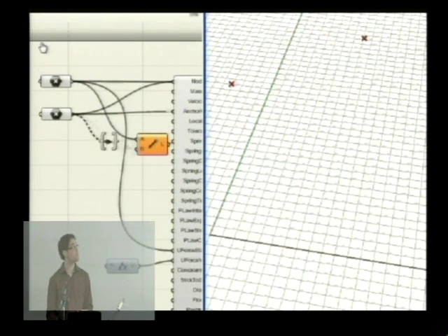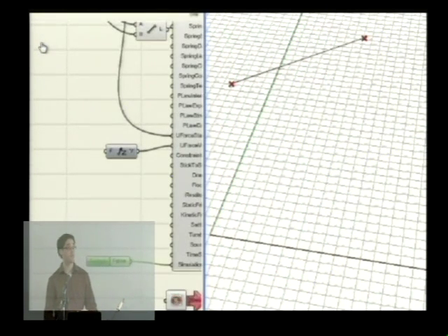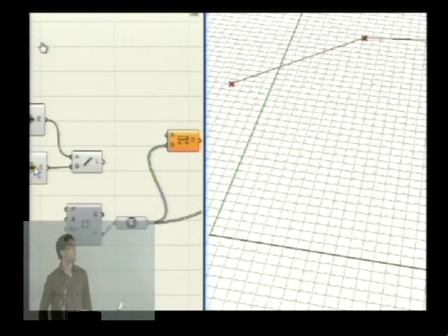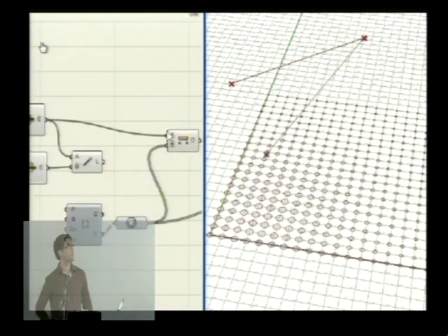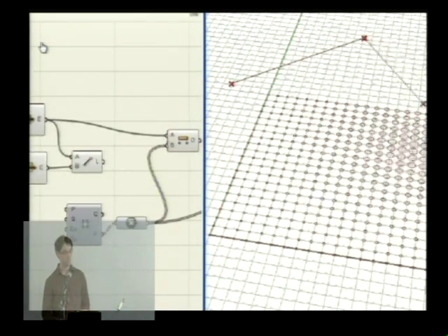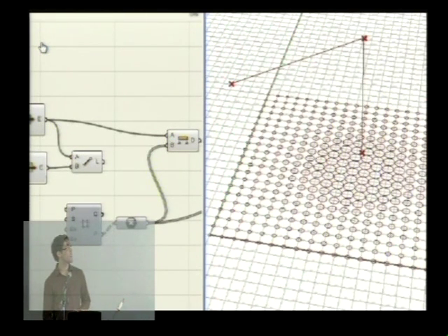Using it through Grasshopper has been the ideal environment to explore this kind of stuff in, because it's very plug and play, and that example is just showing how everything you do in the physics simulation can be connected to the whole of the rest of your parametric model, whatever it is. You can have a bit of physics driving a system which is then panelled using all your Grasshopper tools. And also the inputs can come from anything else you generate in Grasshopper.